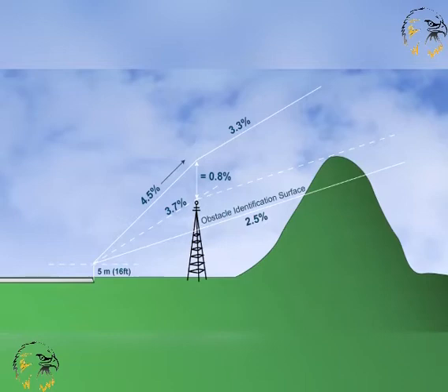If the resultant PDG is too steep, a turning procedure to avoid the obstacle laterally might be the answer. Alternatively, the aerodrome operating minima could be increased until the obstacle can be avoided visually. In the turn initiation area, the minimum obstacle clearance of 295 foot is provided. Of course, in specific areas of more mountainous terrain, increased obstacle clearance will be afforded. If DME is available, additional height or distance information is made available.